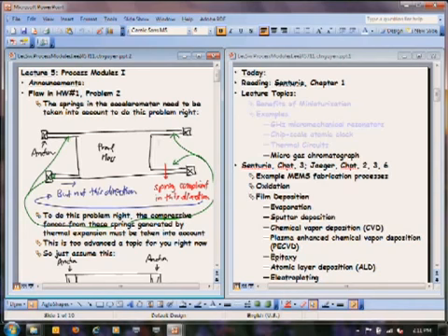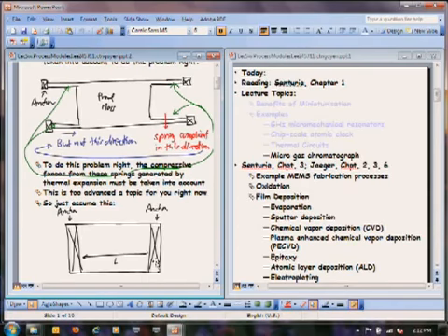So for this problem, just do the following. Don't assume the actual accelerometer like this when you're going to determine buckling of the structure. Just assume that you have that big plate structure where you're given the dimensions, and assume that it's anchored at both its ends. This is a situation where it can buckle, where the equation given for buckling can be used. And all of the stuff you'll do in terms of what the yield of this thing is and all that stuff that question asks, they're valid questions, but not for this accelerometer. They're valid sort of for this here.